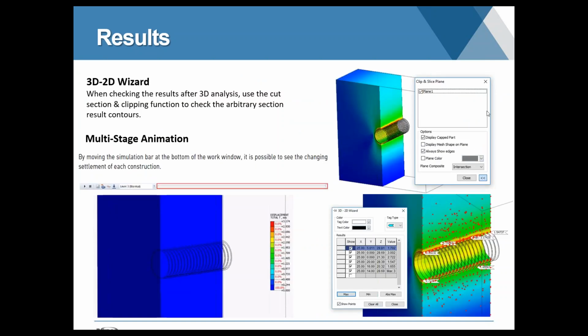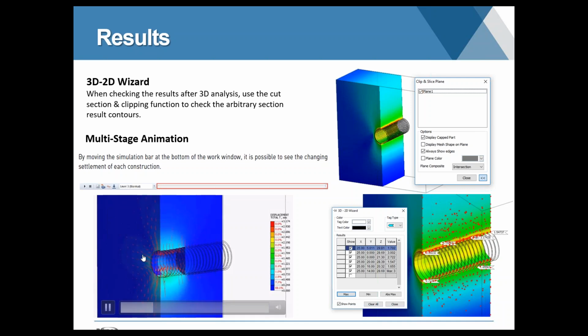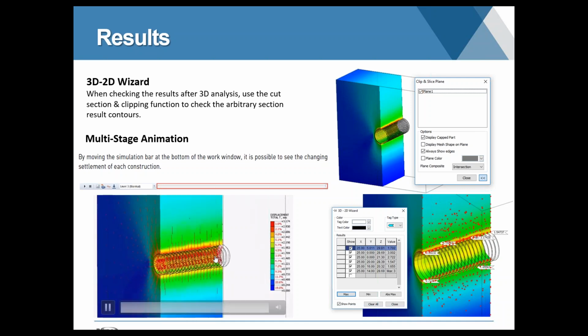And then other things that are important if you're working in 3D, which we saw earlier, is that we can create animations of our entire analysis. Under the bar that we were using to navigate back and forth, there's a little camera and then a play button that would allow you to generate this type of animation.